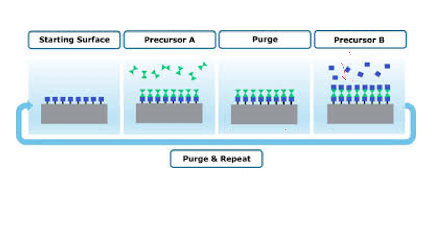Okay. Is there any doubt regarding this? What is the maximum thickness possible using ALD? I think it may be in the nanometer range, not higher than that. We cannot grow micron films. It will be a few nanometers range. That's the maximum we can go. Okay, less than 10 nanometers. Less than 10. Okay. Thank you.